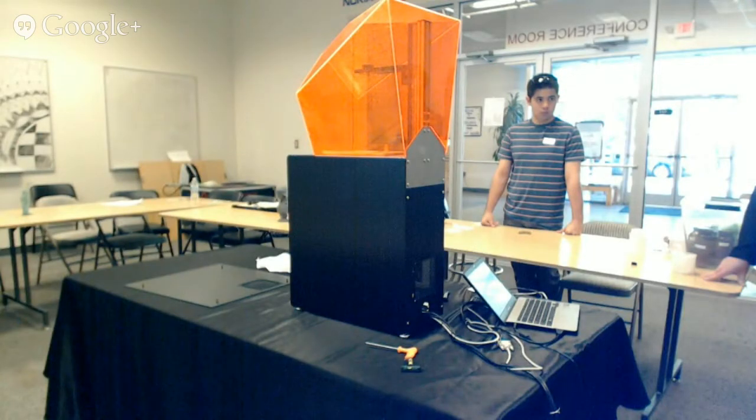The big flaw is that warping is way worse when I printed it sideways, because the force holding the thing flat was much weaker. When I print like this, there's a massive force holding this thing flat. It was really hard to get this off the build. That was a good sign, because there was a huge amount of adhesion holding it flat. Printing sideways, the yield is better. Almost every prototype came out, but they all had weird flaws. But it's easier when you're learning to start with a flawed part and tune it until it works than to have nothing, and then wonder what is wrong with this. I got nothing.